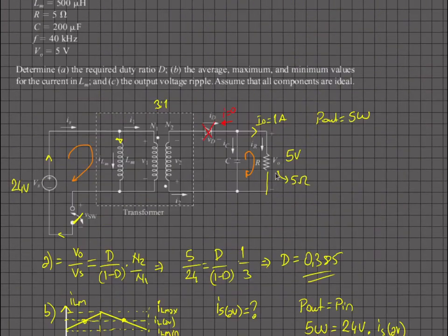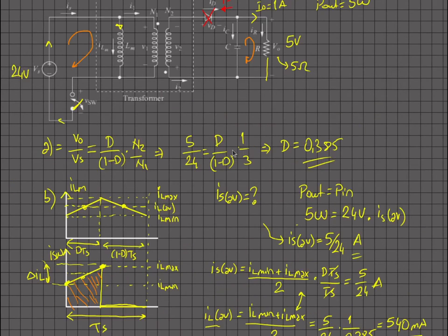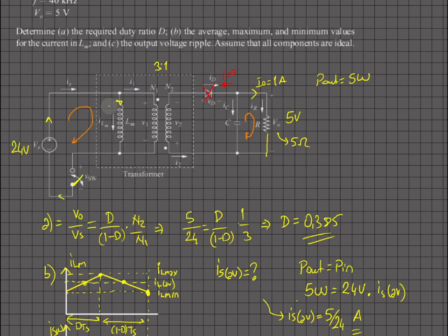Why is it not possible? Because let's have a look at the circuit here. During the charging period, you are closing the switch and your Lm current is increased as it is being charged, and we are looking at that part, the end of our duty cycle. During that part, the current is being sent, you are charging your capacitor and also supplying your load, and then that current is going down and down.